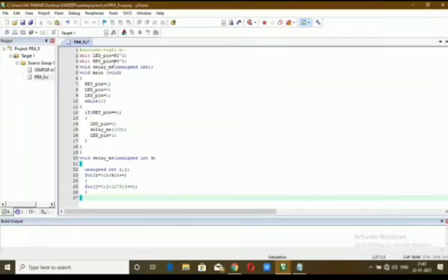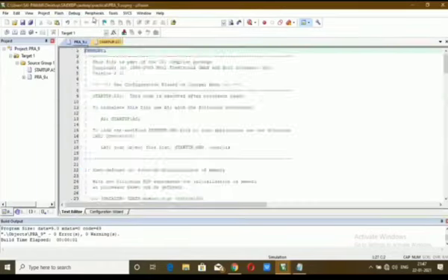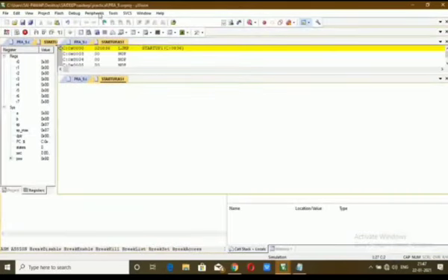We are using port 0 and port 2. Port 0 is connected to the key which will be pressed, and the LED is connected to port 2. Now we are checking whether there is an error in the program. As we can see the program is error free, so we can go ahead to start the debug session, and we can go further to run our program.